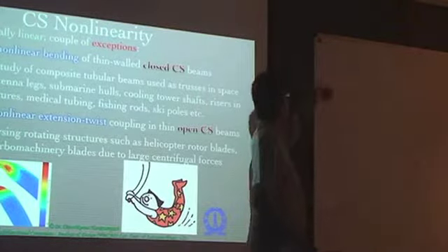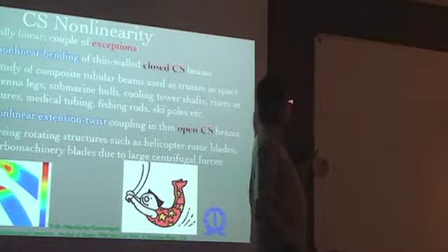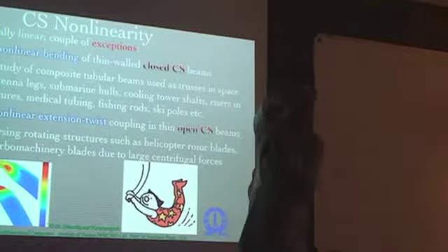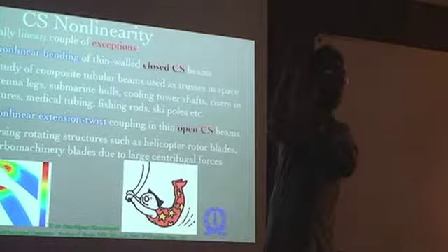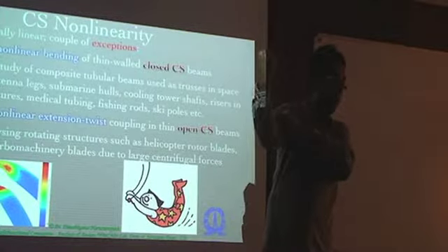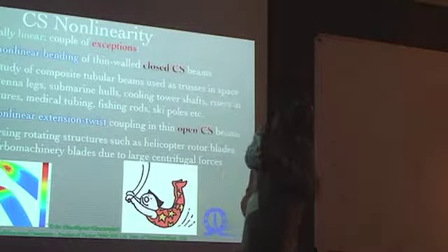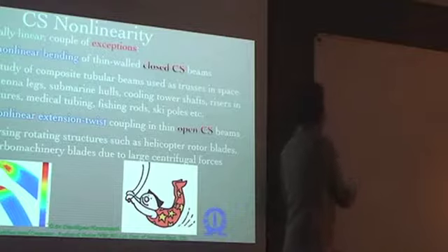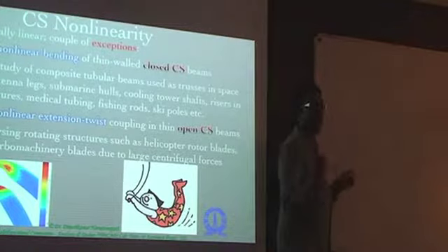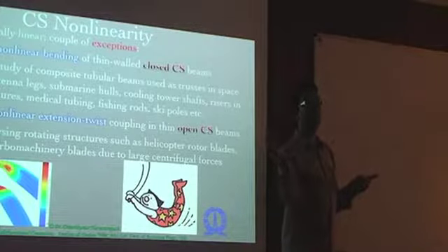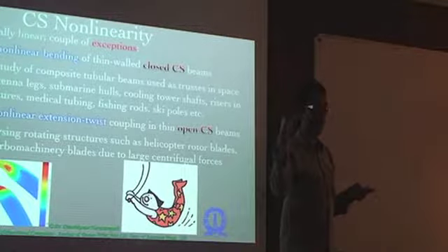See, it is the extension which is causing this. It is the bending loads which are causing this, including the loads that you are talking about. The landing gear load is eventually going to cause the bending of the wing, right? If the landing gear is on the wing, basically it's going to cause a bending of the wing. So if some of these matrix elements depend on, in this case, let's say along the chord you have x2 direction, so you're basically creating a M2 kind of a bending.